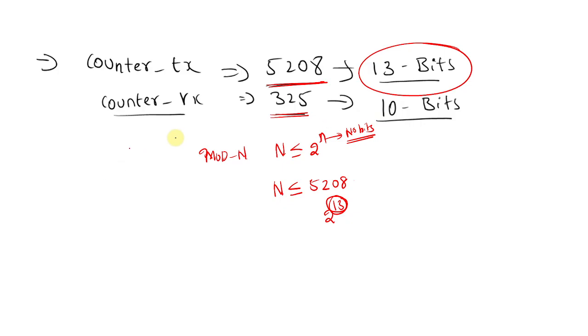We'll see this in counters also. We discussed how to find the number of flip flops. Suppose a 3-bit counter is there, it will count 3 bits, that means 3 flip flops are required. So you declare n equal to 3, and this is a mod 8 counter. Actually this is the mod value.